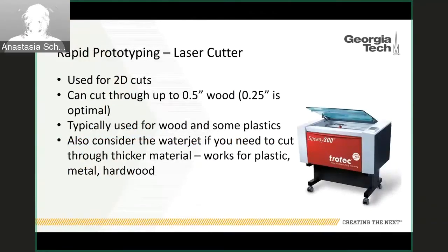You're probably familiar with these from training, but I'm going to go over a little bit of how to use them to your best advantage in this class. The first one is the laser cutter. Of course, you use it for two-dimensional cuts, often wood. We're going to use 1/4 inch wood generally in this class, but it can go up to 1/2 inch with the right settings. Although it's usually used for wood, it can also cut some plastics.